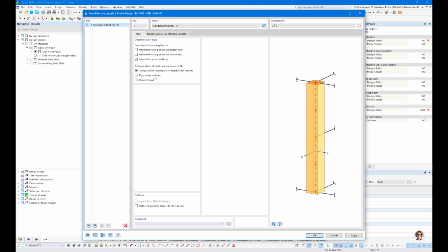Additionally, we have an eigenvalue solver included, which I will show you afterward. It helps you consider more options than the settings described in the Eurocode, which is really limited to uniform loads, simple one-span beams, and so on. The eigenvalue solver helps by not using these tables from Eurocode and determines the critical bending moment in a common way.